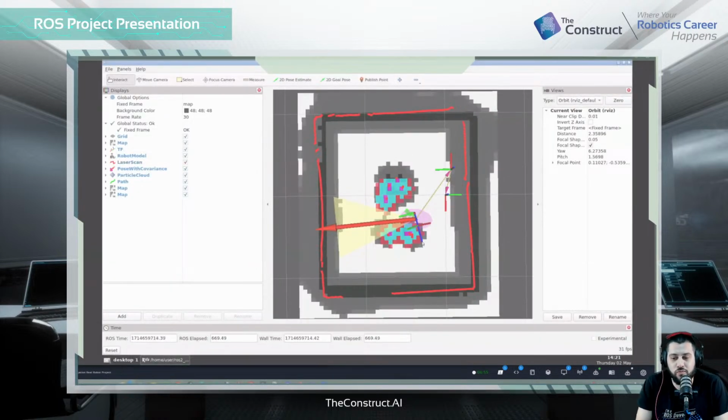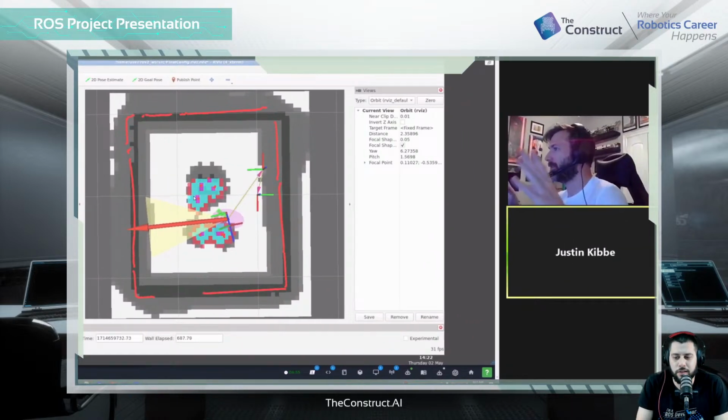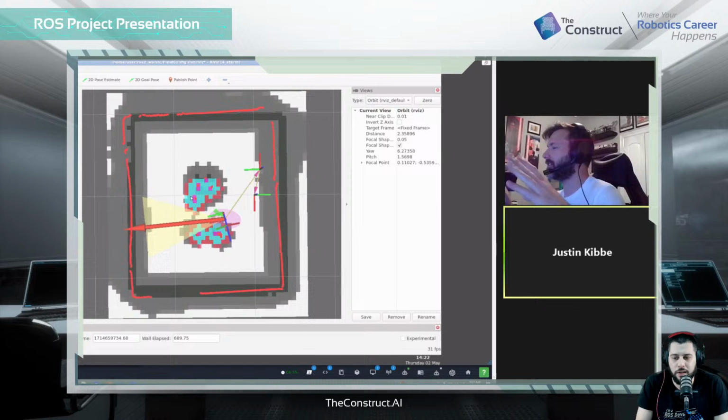RViz, when you start off with the basic default tolerances given in the program, this whole map is blacked out. So you have to go through and adjust the inflation layers on the object. That was another thing I didn't do initially. I just had the map and where it thinks the objects are, and I adjusted the inflation layers until it all works out.